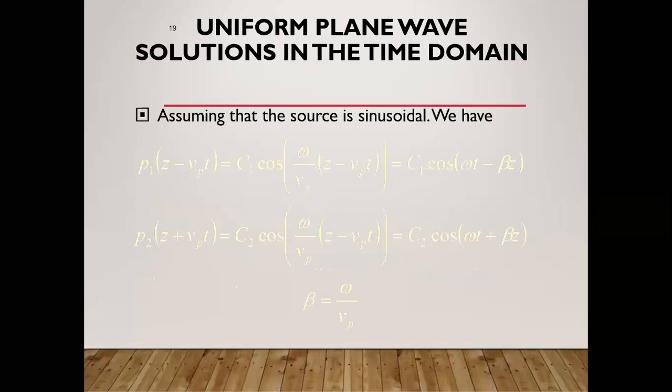So now here, what is the additional parameter which we are going to calculate after the velocity of propagation as well as the intrinsic impedance? That is nothing but the beta. Already we have studied in the network analysis that gamma is equal to alpha plus j beta, where gamma is the propagation constant, alpha is the attenuation constant, and beta is the phase constant.